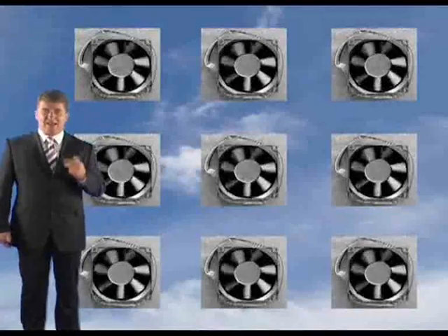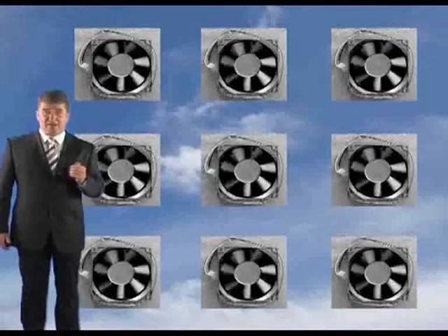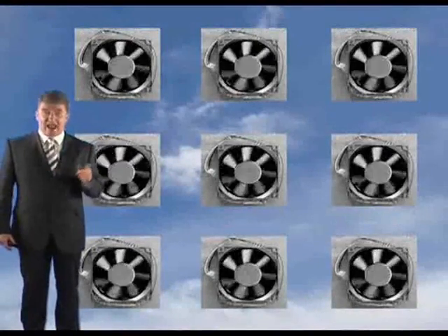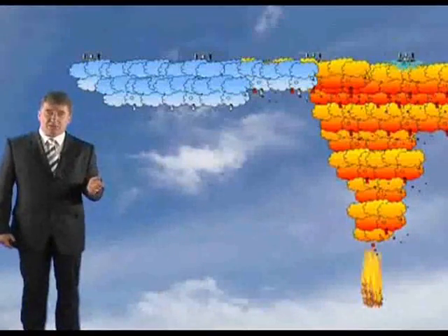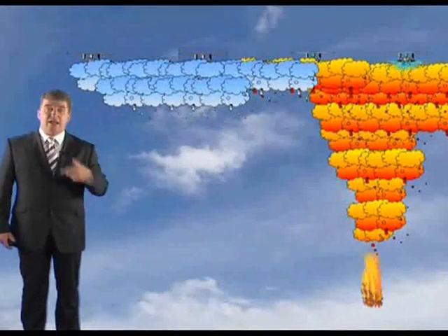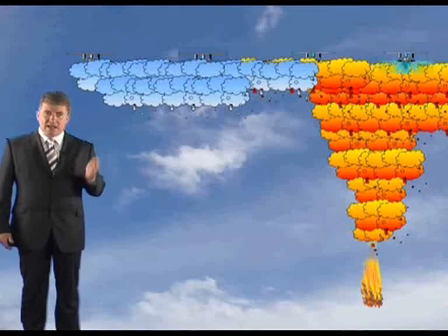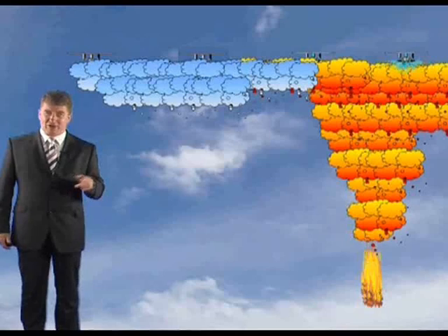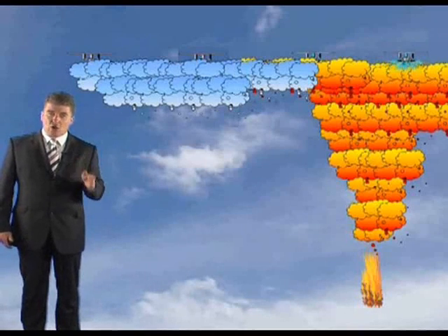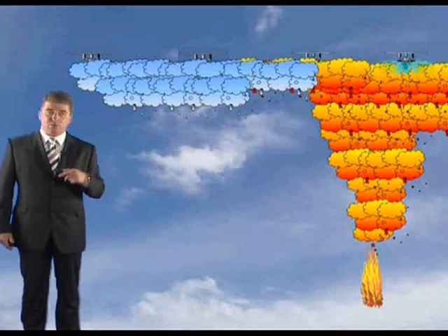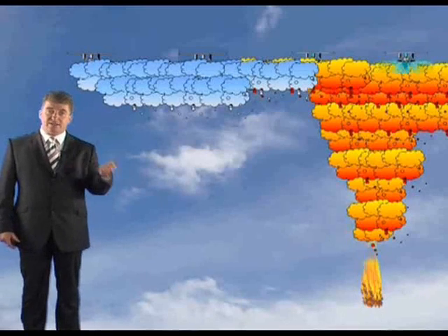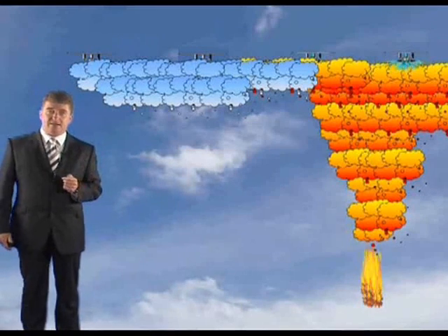Now, what about with mechanical ventilators? Well, with mechanical ventilators, you don't have to work out the area of the ventilators. You have to determine the volumetric flow rate of spill. You have to work out how many cubic metres of smoke are going to come out a second. Now, when determining the volume extract rate required for fans, you can ignore the cooling of the smoke, and this will result in a safety factor. So if you don't take it into account, it's a bit of a safety factor.